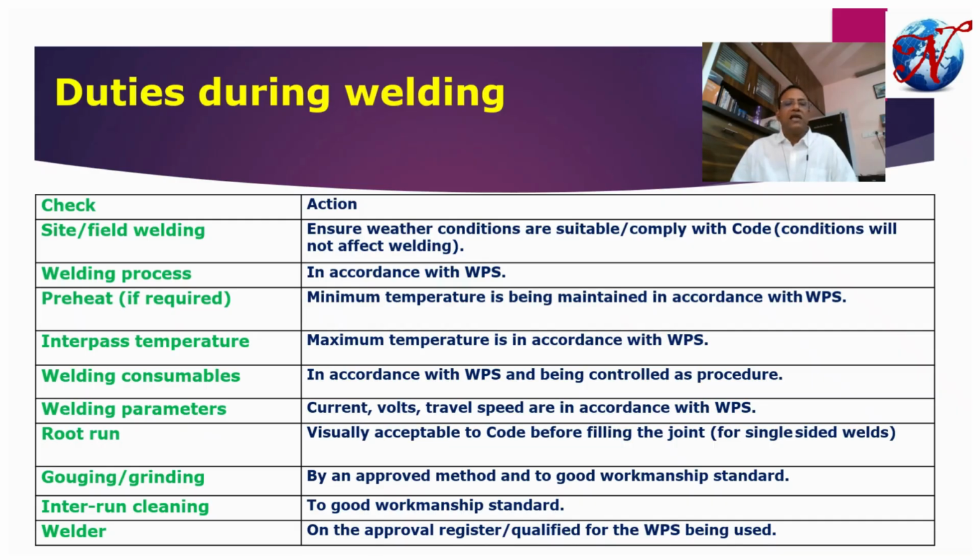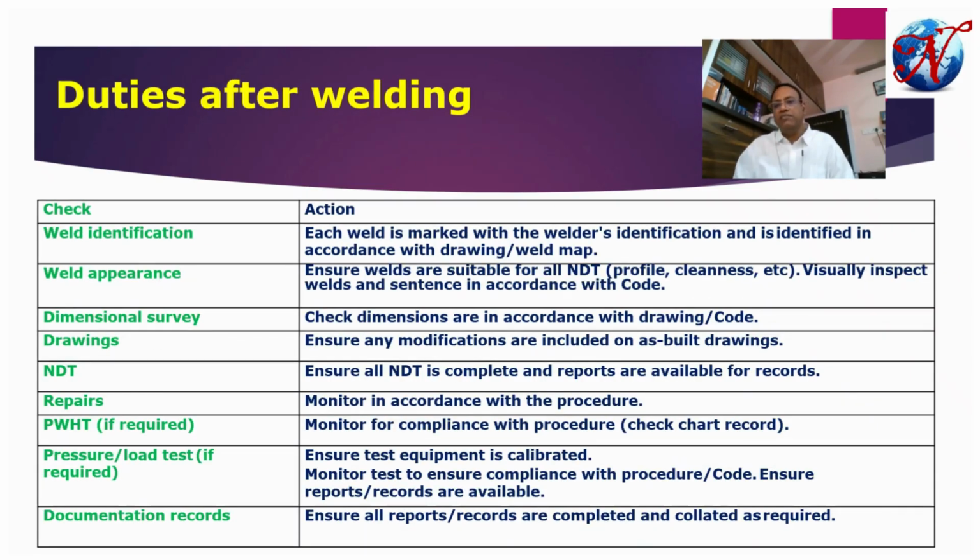If any kind of grinding or gouging requirement is there during the good workmanship standards during the process of welding, that needs to be checked and verified. Internal cleaning needs to be done to remove the slags and others. And the welder, approved, registered and qualified welder, whether they are performing their duties or not, needs to be verified by the welding inspector during the course of welding.